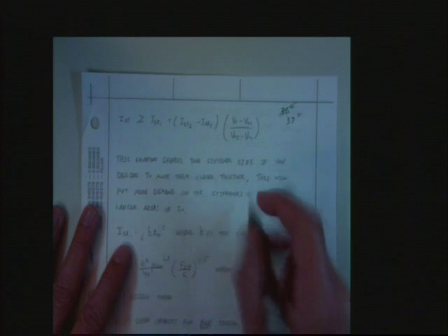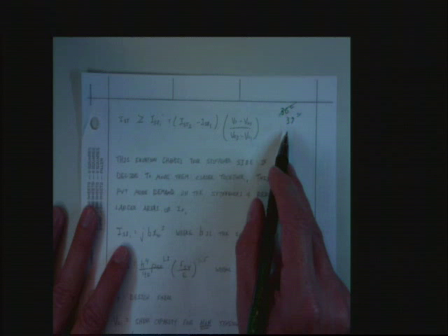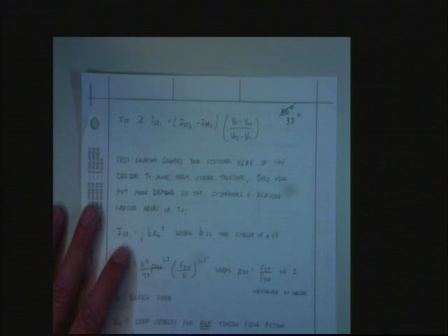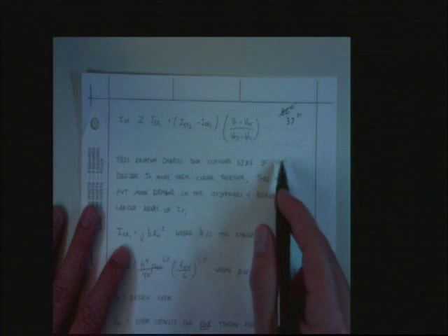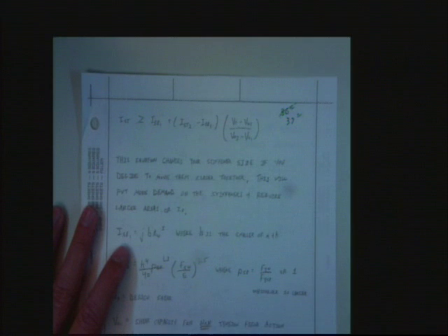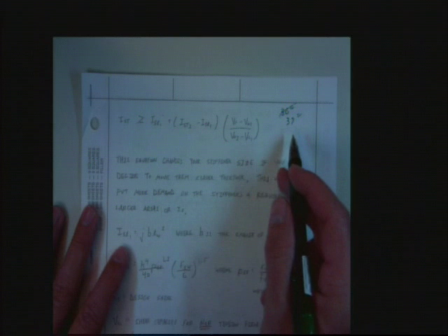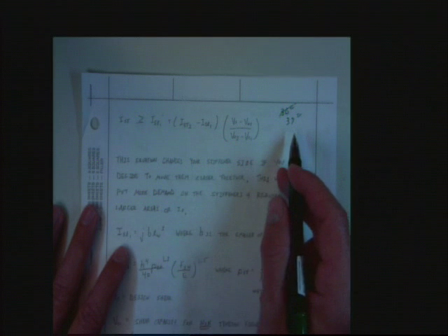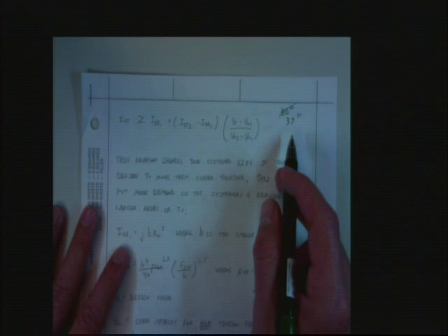About the same. Maybe that fits the girder, so all those stiffeners are at equal spacings or something like that. So you chose 36. You chose some number that's really close to that. If you do that, then all previous equations were great estimates of how much strength and stiffness you needed from your stiffeners.